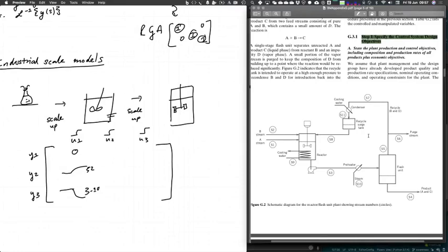And we start by understanding the control objectives, right? So if we want to control the level on a tank, we then figure out a strategy. But if that tank is a buffer tank, and actually what we really want to do is control the flow coming out of that tank, we have a different control strategy, right? And the kind of model that we set up also changes based on the kind of strategy that we have.